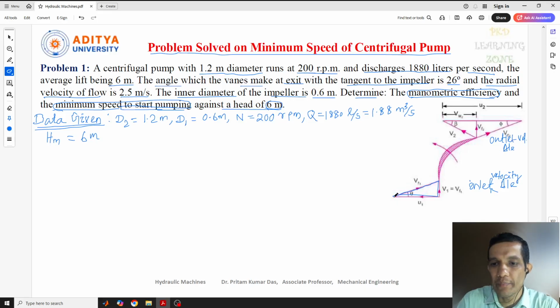At the inlet, very simple, it is like the water is striking into this vane. This is the vane, or the blade. So the water is striking perpendicular to this one with the absolute velocity v1, and this is the tangential velocity, or if you draw the tangent to this one, like this, the tangent is there. So the same thing, tangential velocity u1, which makes an angle of theta to the relative velocity vr1.